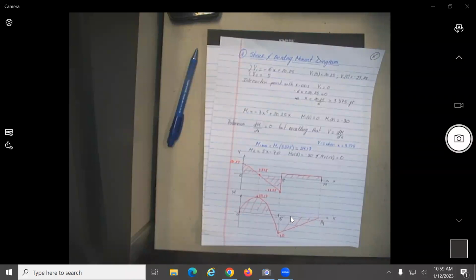Generally, how do you determine the deflection? Deflection generally is given by M of x divided by EI, and you integrate. So basically, the deformation is related to the bending moment. Can the deformation not be continuous? The deformation of an object needs to be continuous, no? Yeah, if it's not continuous, it means that it has some type of a break.